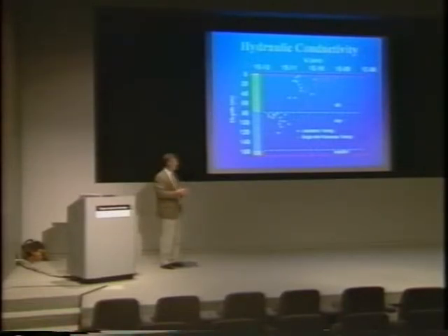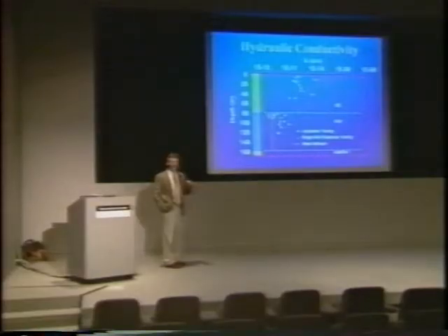We did that by knowing the hydraulic conductivity of the till, the hydraulic gradient in the till, and the hydraulic gradient in the clay aquitard material itself, and we calculated the hydraulic conductivity. That hydraulic conductivity corresponds to a velocity of meters per 10,000 years downward. These numbers for hydrogeology are extremely low. In terms of geologic scale, they're not that great, but hydrogeologically, they're very low.